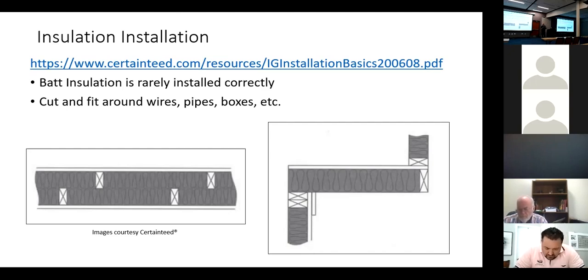So building science, we have a whole bunch of things we need to think about. We have to think about our air quality. We can't just make it airtight without ventilating it. I'm firmly of the opinion that you cannot make a building too tight as long as you ventilate it, and you ventilate it correctly. I mean, insulated concrete forms, ICFs.